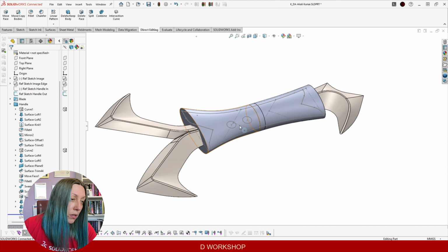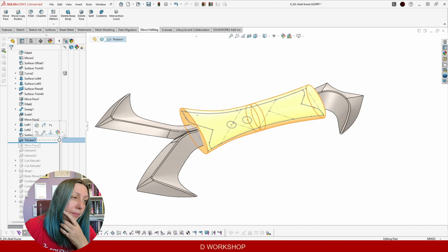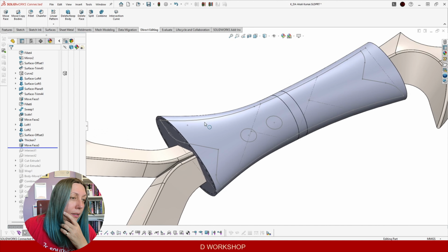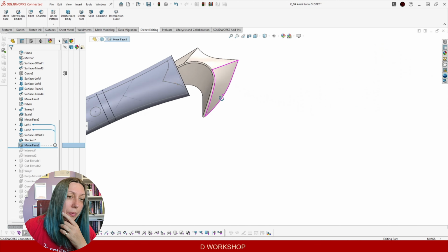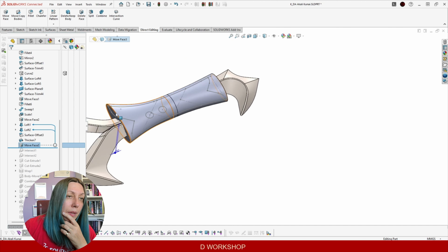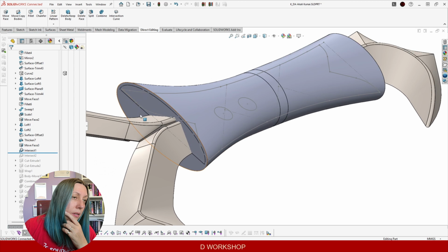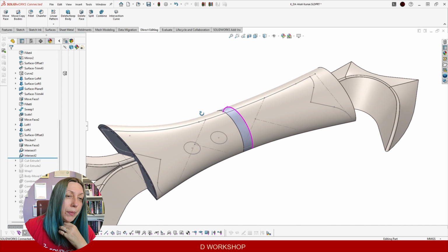I will use surface offset to create another part. I will thicken that part and then move the end faces of the thickened part so they are flush with our model, and I will use intersect 2 times, once to have the half of the inner part and once to have it from the outer part.